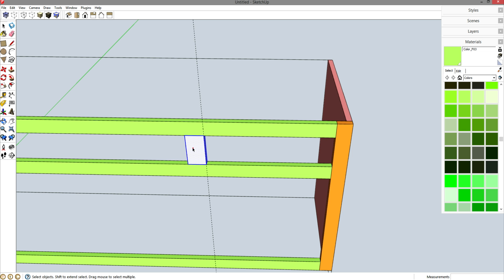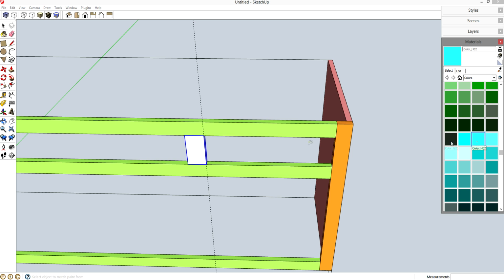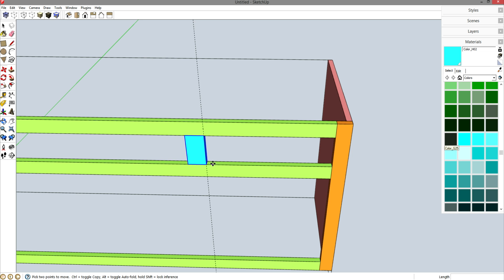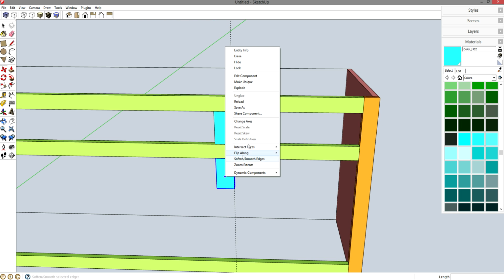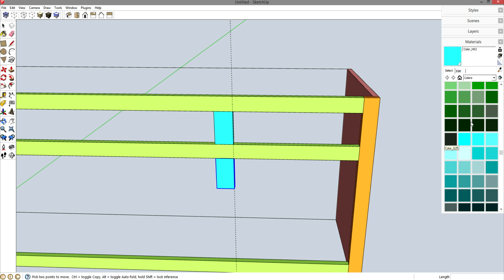If not, things will start to look crowded in the middle. Spacebar, triple click, G for component, enter. And let's just drop another color like we've been doing. M for move, control brings up copy, and I'm going to copy this one right down here because it's in the correct orientation, the correct shape, but I'm going to right click and say you are unique. You are no longer a copy. That way I can change the color real quick.